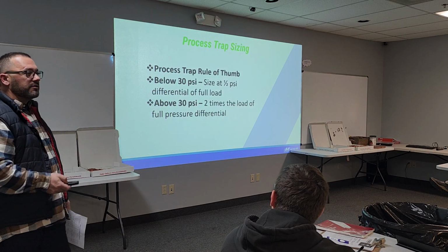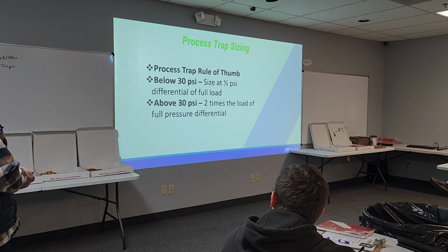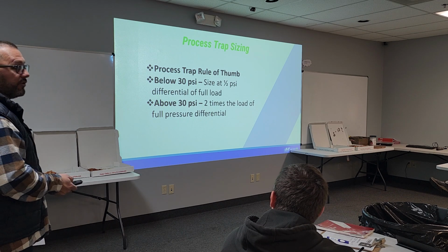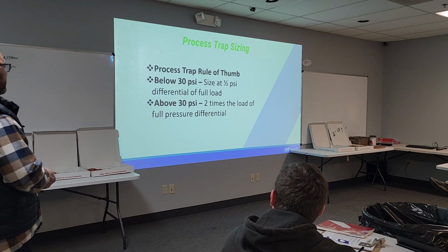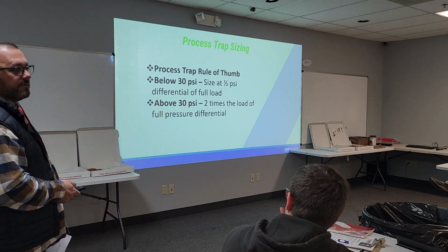There's safety factors. Or, a kind of rule of thumb here is below 30 PSI, size at a half PSI differential of full load. And when we get above 30 PSI in process applications, we're sizing 2 times the load at full pressure differential.